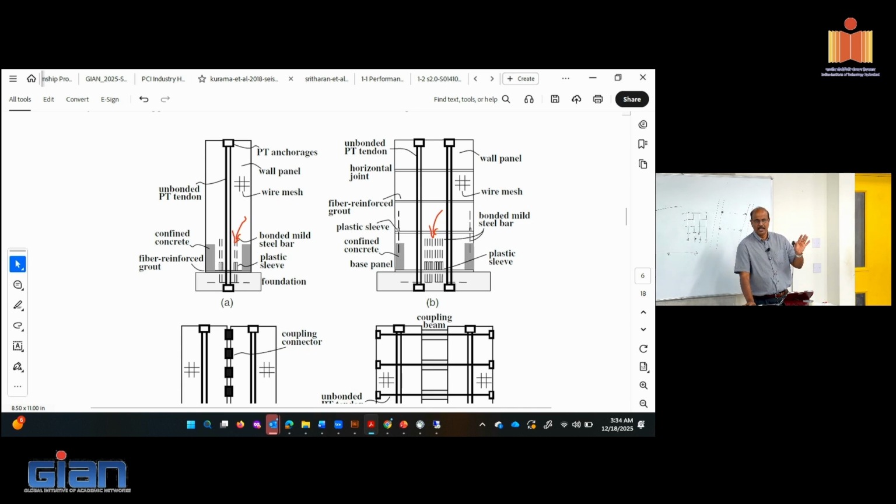In cast in place, they both are connected together, right? You design the amount of reinforcement based on strength. By doing that, you already fix the amount of damping. You don't have a way to control that, because that inelasticity is what translates to a certain percentage of inelastic damping. All you can do is quantify and say how much damping we have, and that's where the 25-30% number came about.